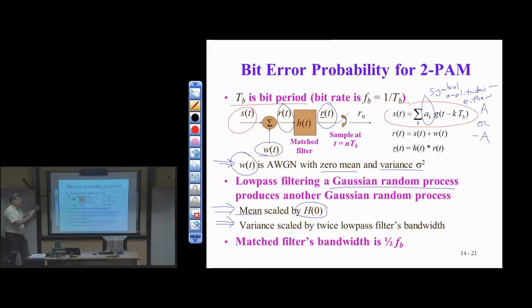Well, we're still in continuous time. We're about to sample, right? All this is in continuous time, and then we're about to sample. So what's that low-pass filter doing before the sampler? The sampling will replicate the frequencies. It's attenuating. We'll stay on one particular bandwidth. Still looking for the right phrase, but the descriptions are correct. This is the anti-aliasing filter for the sampling operation.